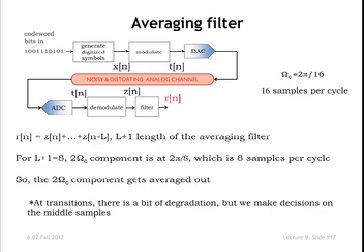So the filter here, the simplest one, just puts out a signal that sums L plus 1 of these values, where L plus 1 is 8. That's exactly the period of the double frequency component. Remember, we had 16 samples for the original carrier. So the double frequency component has a period of 8. And so the 2 omega C piece gets eliminated.